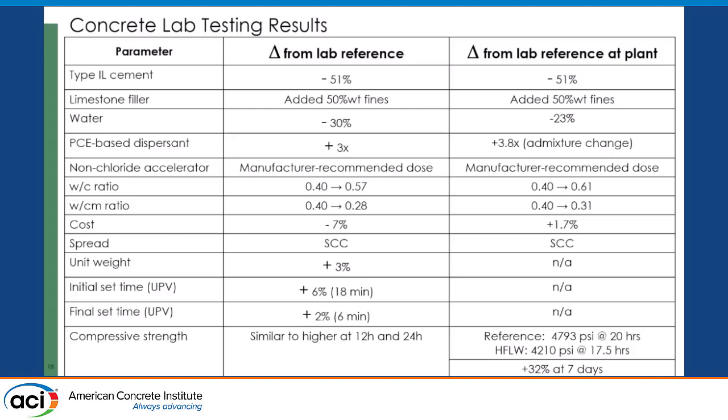SCC, and here are some strength results. They tested the reference and the high filler at different times. They had some confusion there at the plant, but you can see the reference was 4,800 psi at 20 hours. Ours was 4,200 psi at 17.5 hours, so it was not at the same time. So probably this is getting closer to the reference here, but at 7 days it went way higher, 32%. Okay, so this is an ongoing effort.